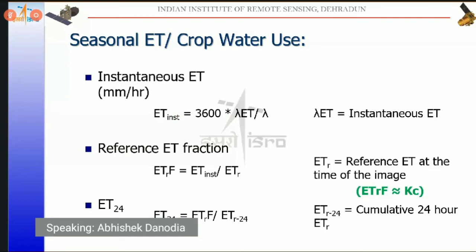And especially for crop water requirement, they use the precipitation data sets to define CWR, crop water requirement. So this is a whole nutshell regarding the seasonal evapotranspiration data set calculation, starting from the one source model and two source model respectively, and ultimate calculation using the reference evapotranspiration data sets for seasonal crop evapotranspiration or crop water use at crop specific areas.